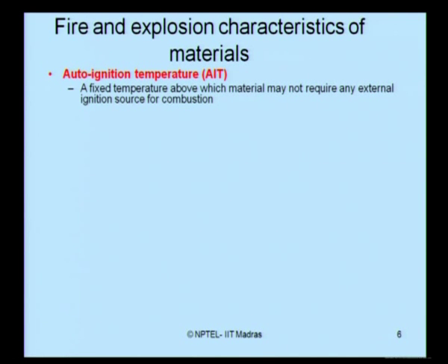So in our own interest, if you know the AIT of the inventory material which you have stocked on board, try to see that your operating temperature does not exceed this fixed temperature, the AIT of the material.